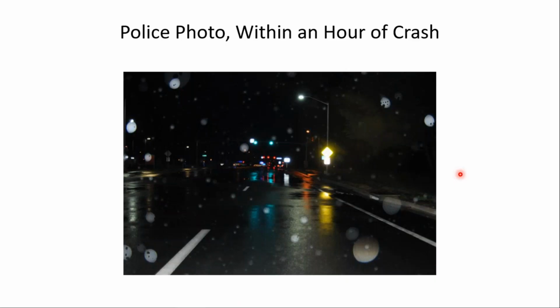But notice in the photo, you can't really even see the crosswalk markings. I'm not sure if that's due to a retroreflectivity issue with the marking, or you can also see there's a lot of reflection, because the pavement is wet, and you're seeing other lights and things in the water puddles on the surface.